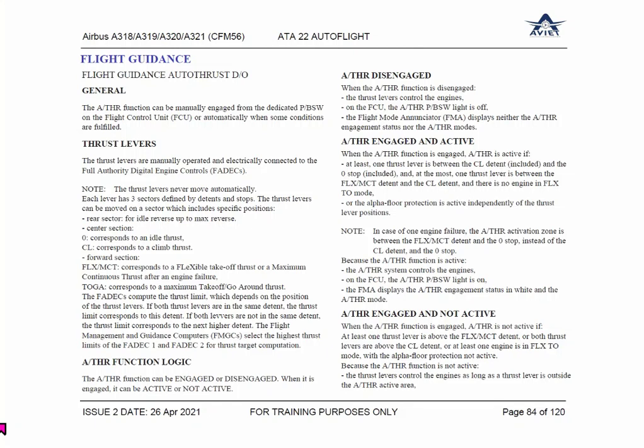No problem. So engagement means it always checks the inputs connected, outputs connected, as well as the software, the required system. If you go for the autopilot, there are many conditions, many computer inputs, many switch positions. It will check everything is in line or not. And the moment the aircraft is in flight, after liftoff plus 5 seconds or 50 feet above the ground, then it will be active.